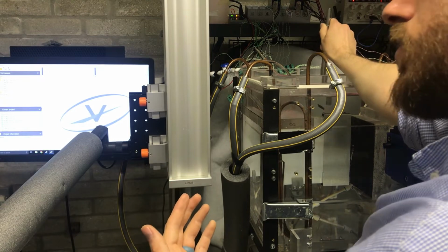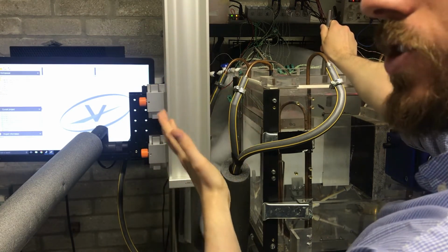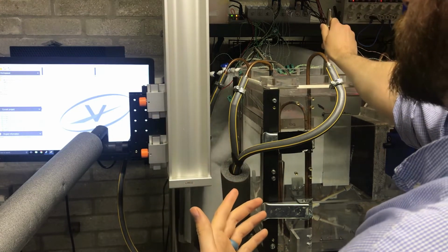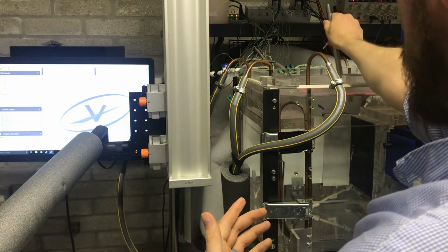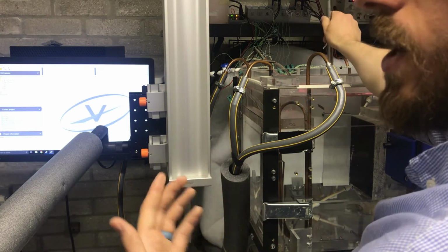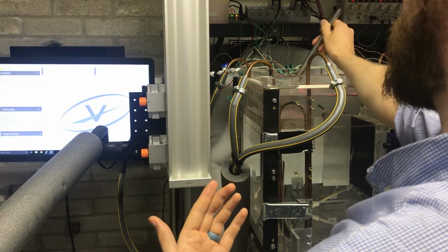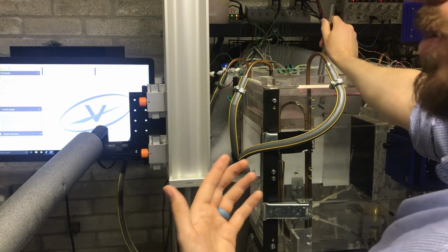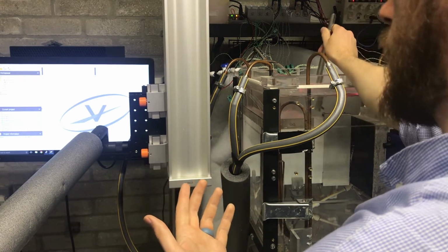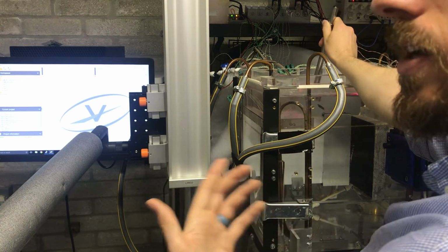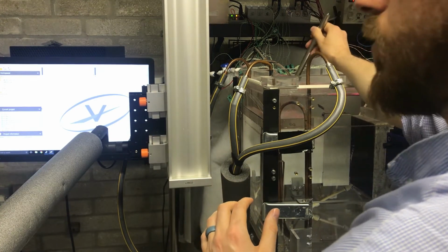And why that's important is near to a surface you get a massive amount of reflection of the laser light, the 532 nanometer green light, to the point that it completely obscures the reflections from the seeding particles. One way to get around that is to have an emission from the seeding particles in a totally different wavelength. So actually we'll be emitting some sort of yellowy orange colour rather than green.